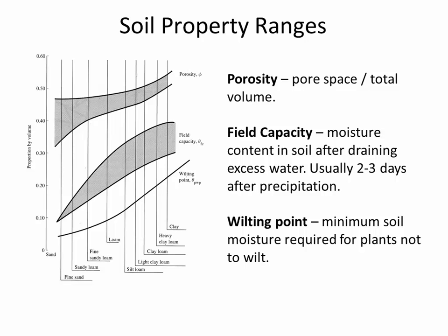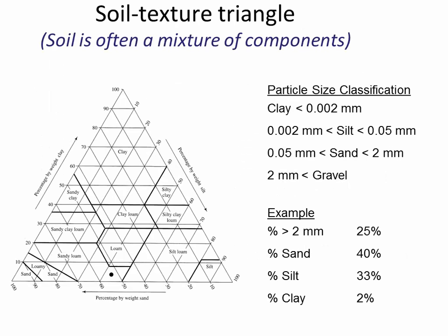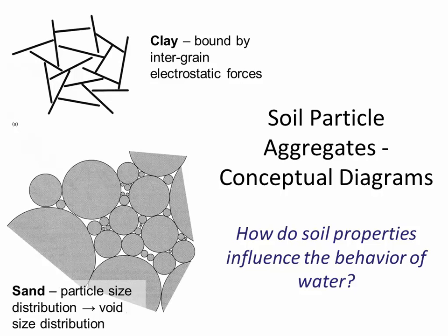So porosity is talking about the pore space relative to the total volume. If we go back to this figure, porosity is saying how much empty space there is compared to the total area altogether. And so if I drew a unit volume, porosity is going to be a measurement of how much empty area there is inside of that unit volume. So if I draw a cube, and now I'm going to measure inside of here how much is solid, how much are the spaces relative to the total volume. That's porosity.